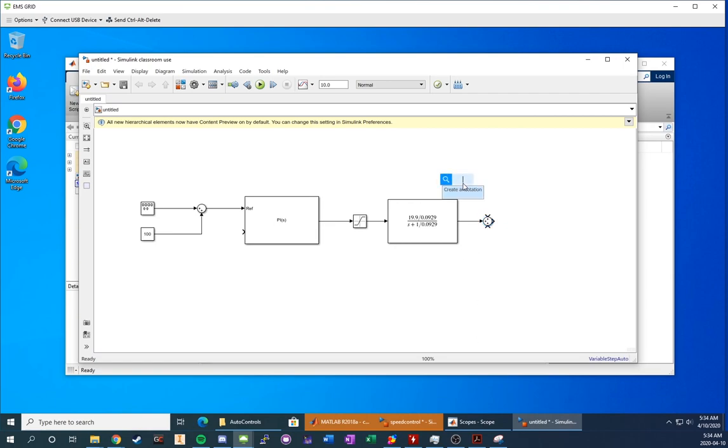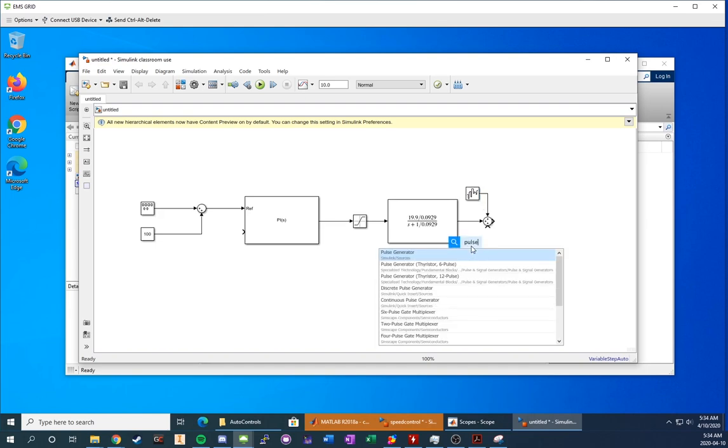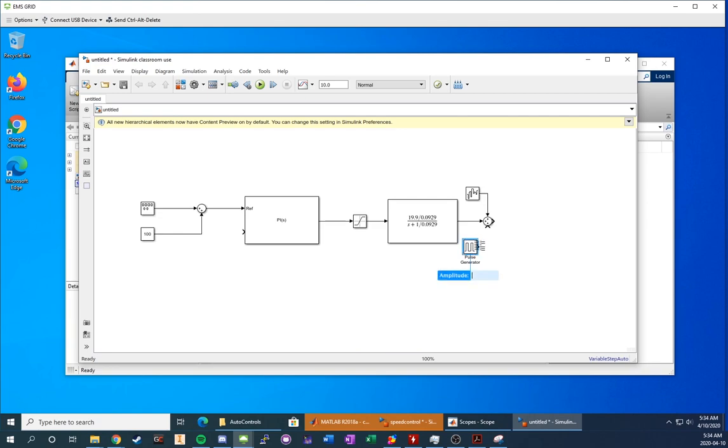On the top, we're going to have a white noise generator, band limited white noise, and just set it to a power of 0 for now. We probably won't be using it when testing this lab, but it is very nice to have if you want to check the robustness of your system. We'll be doing a pulse generator, and we're setting it to 0, but this determines a lot of things when you're trying to put your disturbance into the system. It's nice to have a pulse that we can control the length of as well as the amplitude.